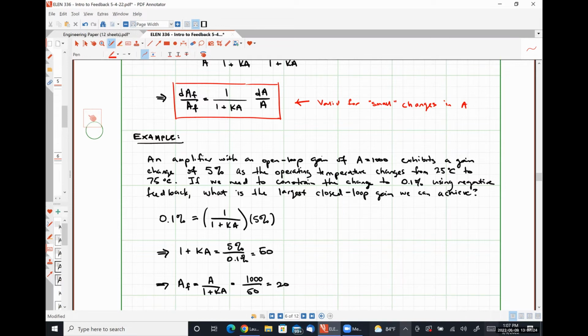So when I had a loop gain on the order of tens, a 90% change, still the math worked out to be the same using this method or the direct method. When my loop gain was very, very large, say on the order of 10,000 or so, after about 20%, the numbers diverge pretty wildly.